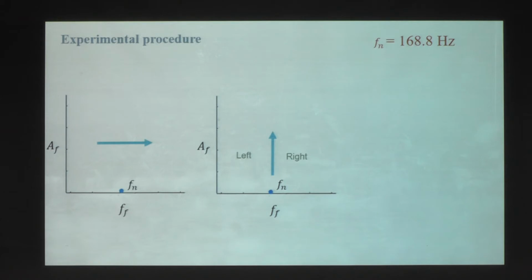We are going to check the interaction between the self-sustained oscillation in the Rijke tube and the forcing oscillation. Here comes the theory of synchronization, because we now have 2 oscillators. Once thermoacoustic instability sets in, we can consider the system as a periodic oscillator, and the external excitation, which is again sinusoidal, can also be considered an oscillator. So now these two oscillators are interacting, and this interaction is unidirectional because it's a forcing. Forcing will affect the system, but the system will not affect the forcing.